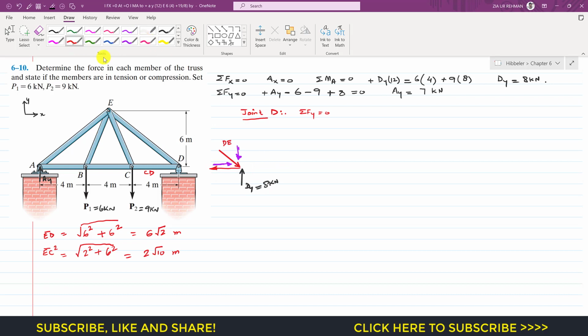So this is joint D here. So here we have that theta, right? So again I have to draw that triangle. Let me have that triangle as well. So the summation of forces along y. If this is that theta, then this one is the sine component. So we can write that DE sine theta component is acting in the negative y. This is our positive y direction. So we will write minus DE sine theta plus this Dy, which is 8 kilonewton, equal to 0. If I bring this to the other side, it will become minus 8.